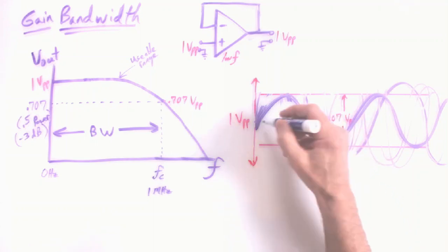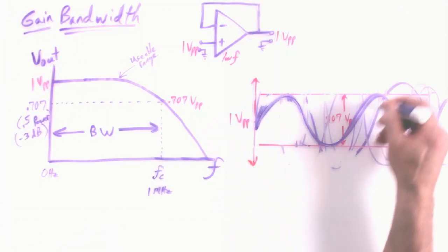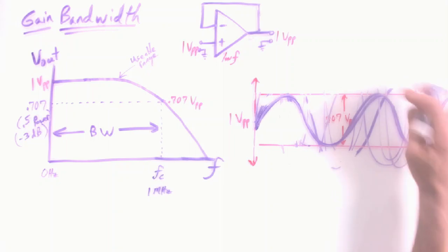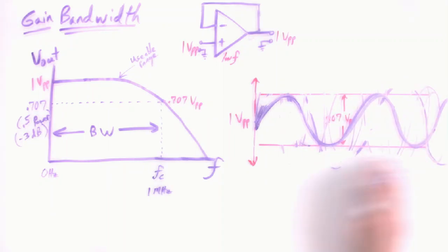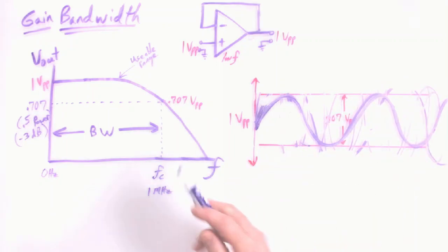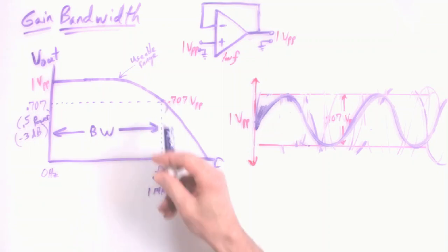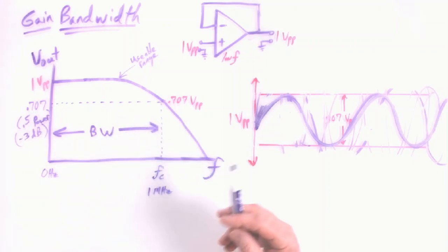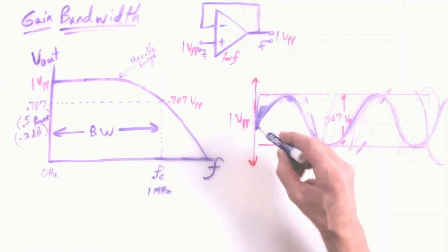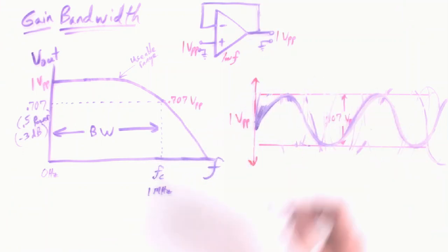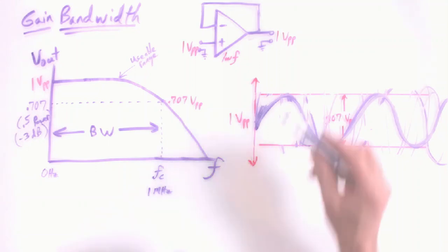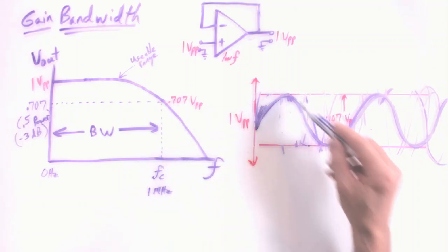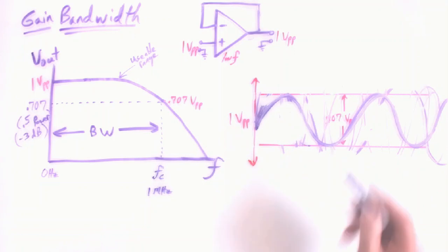But I wanted to really try to do that physically for you because I always get asked or called over to a bench because students are asking me, well, I can't get this to show up on my screen, like I said before. But you're not going to. You're going to get a low frequency sine wave, and then you're going to keep going until you get to a higher frequency sine wave whose peak to peak value drops right within your framed levels of your cursors.